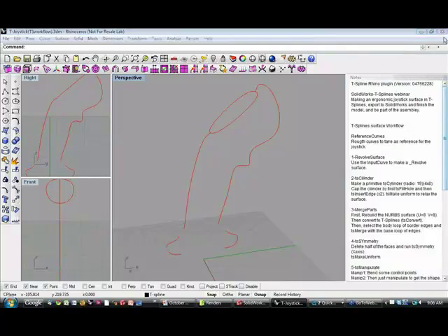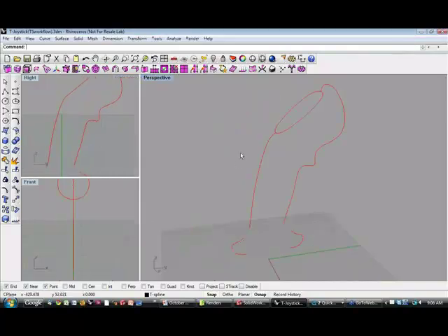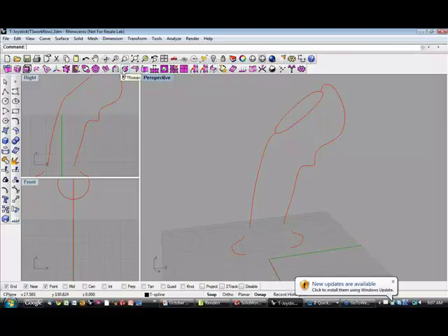And here you will see, this is just a copy of Rhino 4. And the T-Splines plugin is these pink icons in that T-Splines toolbar. So T-Splines is a fully integrated plugin inside of Rhino, and many Rhino commands can be used on T-spline surfaces, and it's very well integrated. So during this demo, we'll show two ways that a T-spline surface can be created to make both the base and the handle of this joystick. And then we'll also show how to merge T-spline surfaces together and how to use T-spline symmetry to explore the shape of the model.